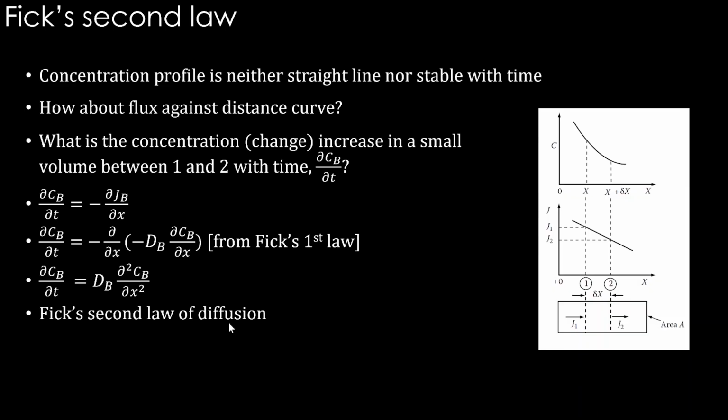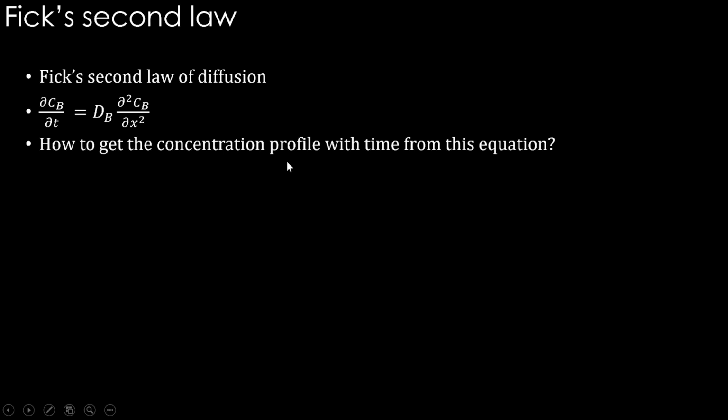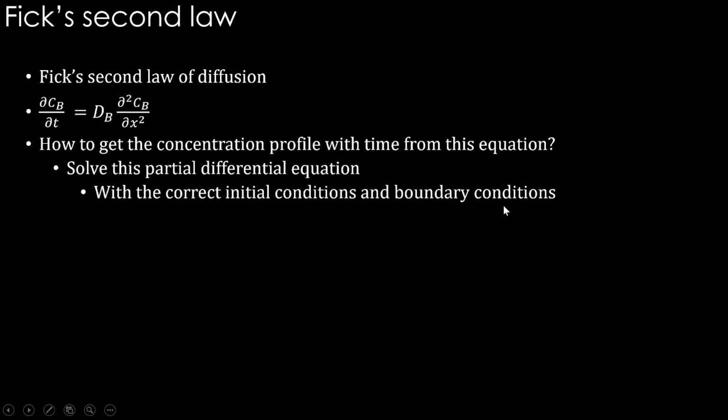So if Fick's second law is available to us, can we predict the concentration profile, how it changes with respect to time? The answer is yes, we need to solve Fick's second law and get this. Okay, Fick's second law of diffusion is there with us. How to get the concentration profile with time from this equation? Solve this partial differential equation. That's what we have to do, with the right initial and boundary conditions.